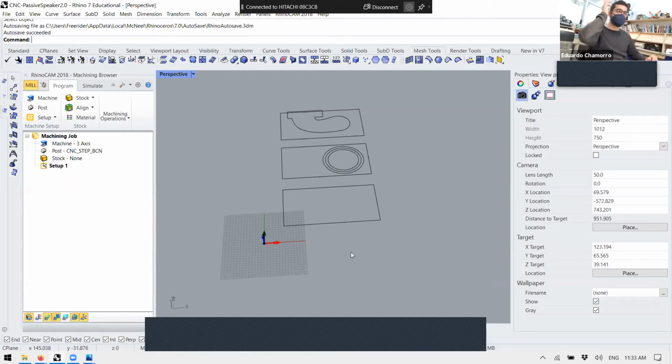Actually, in this machine you can configure a lot of macros, which are predefined things. For example, for this machine, I have configured auto self-cleaning. We go in the menu, and I have a G-code file ready as a macro. When I finish cutting, I take out the end mill and the collet, I make the Z really low, and the machine will automatically brush the whole bed, so I don't need to clean it.